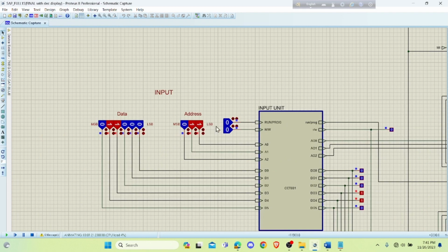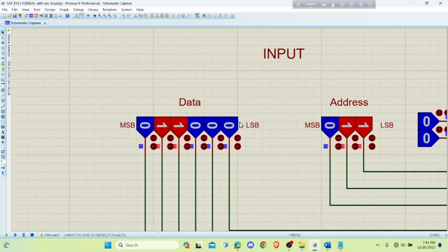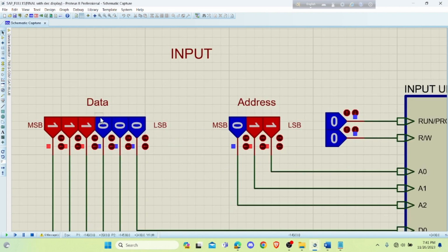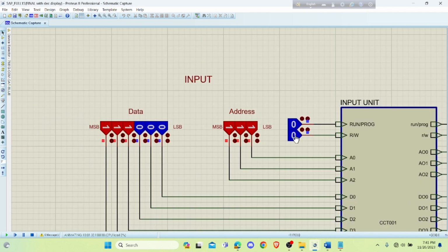And we will give the process as halt, we will stop the process, and for that we will give the opcode as 111. Also here we will ignore the address. For address selector we will use 111. We will run it. So for addition we have got the inputs.